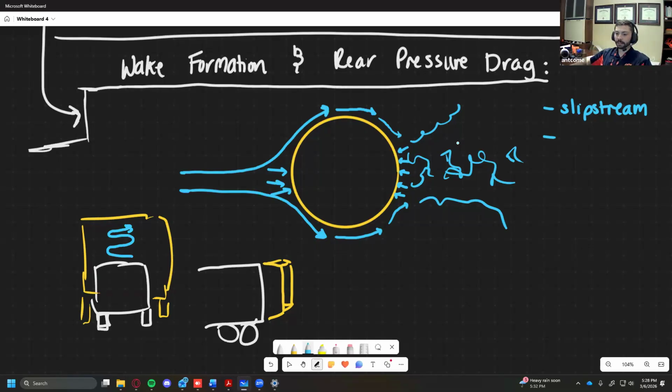It's getting pulled away. So if you think about the net forces, you have this huge force here, which is basically your form drag. You have these forces along the face, which if I were to draw the resultant vector, might look something like this from that skin drag. And then you have pressure that's actually lower here than it is here.